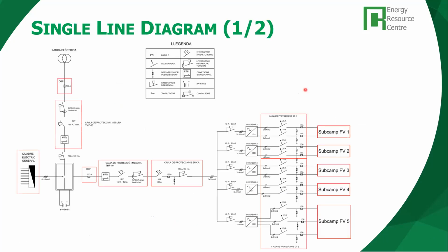The single line diagram, as we mentioned. With this diagram, it's important to mention that the microgrid manager is programmed so that whenever possible, consumption is covered instantly by the photovoltaic installation without going through the batteries. This is what is called instant self-consumption. When photovoltaic production exceeds consumption, the surplus is used to charge the batteries. As photovoltaic production decreases, the batteries begin to supply energy.